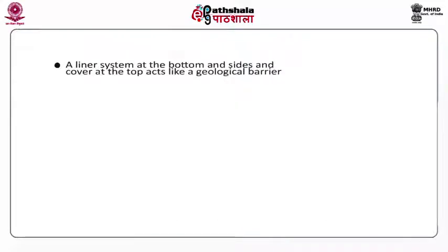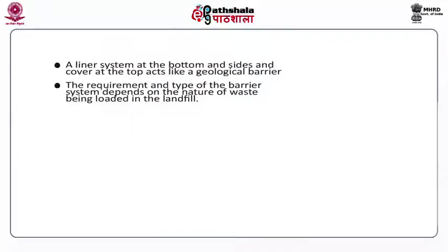A liner system is provided at the bottom, the sides and on the cover, acting like a geological barrier. The requirement and type of the barrier system will depend upon the nature of waste being loaded. Both natural as well as synthetic materials are used as liner barriers.